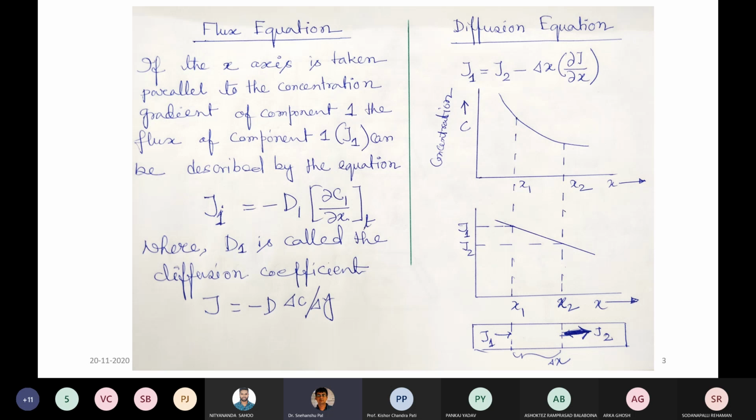So in a lattice with a cubic symmetry, the diffusion coefficient has the same value in all directions. So it is symmetrical, and you can say that the alloy is isotropic with respect to the diffusion coefficient. The assumption of isotropy will be very important, and we will discuss it throughout the subject where we are looking at diffusion. We used to look at the isotropy concept with respect to the specimen. We will consider it during this subject when we are looking at the diffusion coefficient.